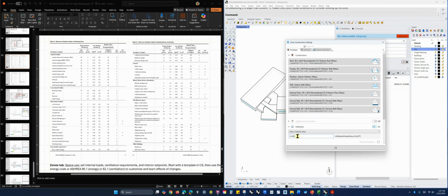0.1 would probably be a good level. So 0.045 is just a very well designed building. It's also, though, since it's a larger building, this is the CFM per square foot of exterior surface. If you have a big volume, you'll have less surface area, and so it's easier to meet a lower number. If that's confusing to you, don't worry about it.